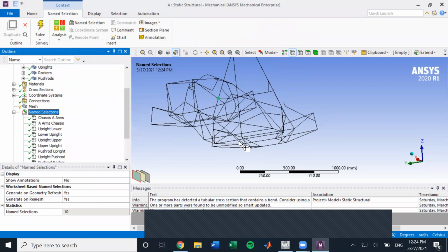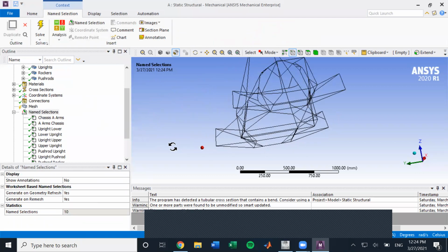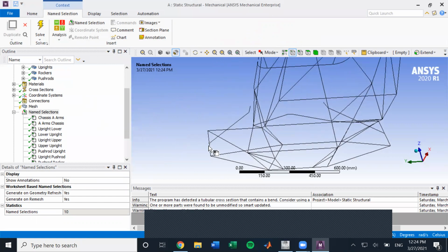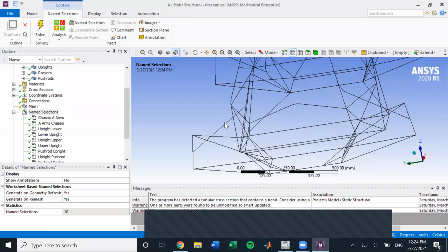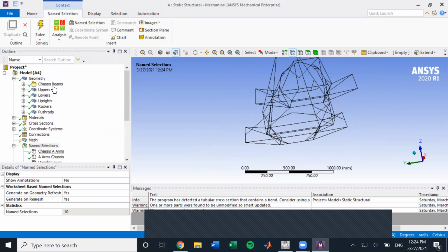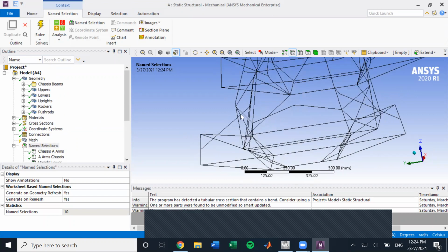If we go through, we can see in the rear now we have the pushrod coming from this point on the upright rather than this point on the upright, which is exactly what we want because, again, remember, this point would just get too crowded with multiple joints that ANSYS, in my experience, hasn't been able to handle. And also I've gone through, and once again, just the way I did that process of changing this position was